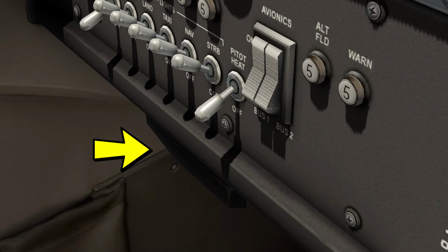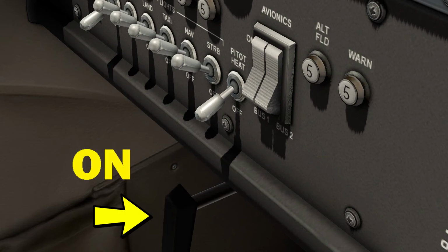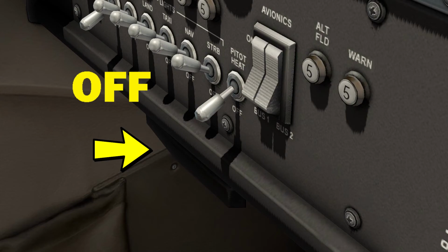Although this is self-explanatory, you may need to be reminded to make sure the parking brake is in the off position prior to landing. Failure to do so will result in excessive tire wear, and if it's on a tail dragger, you will flip over.